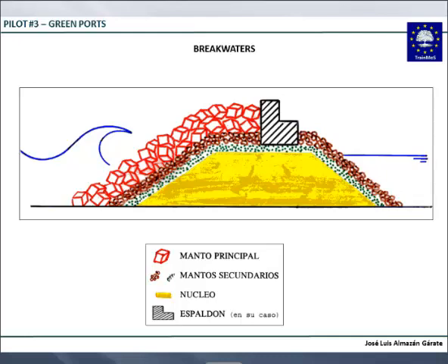So the energy is dissipated in these continuous explosions in these spaces within the blocks. Naturally, the most explosions and the most energy dissipation take place in the area where there is most energy in the waves, and that is close to the sea surface, because the energy of the waves diminishes as you get deeper.